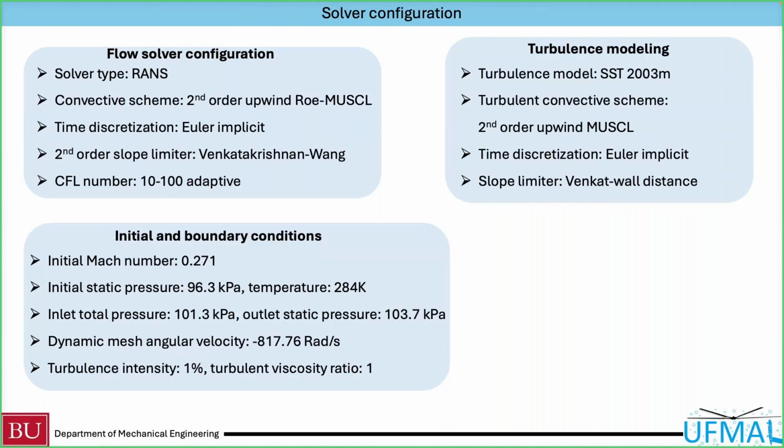Although the intensity matches the experiment condition, the viscosity ratio is lower than what many other people used, which usually ranges from 2 to 40 at the inlet for this application. But in my own experience, a larger viscosity ratio tends to blow up the simulation in this application.